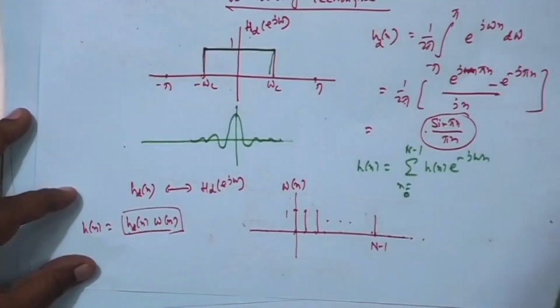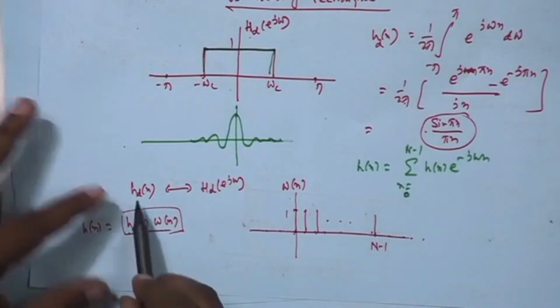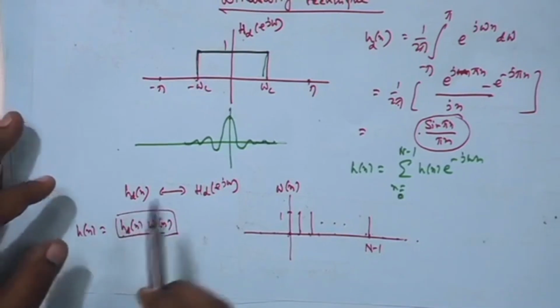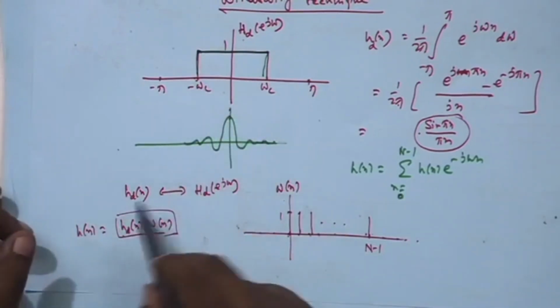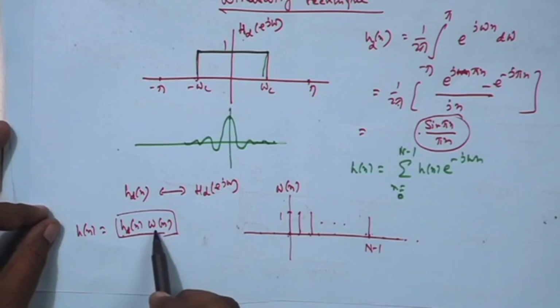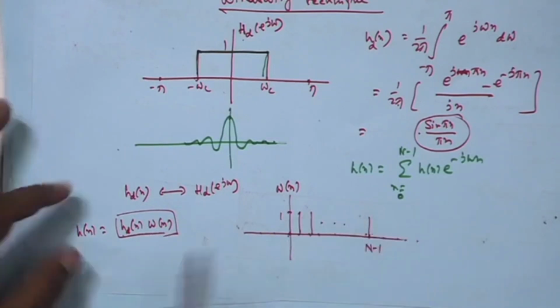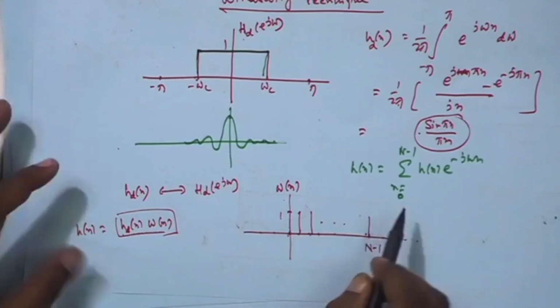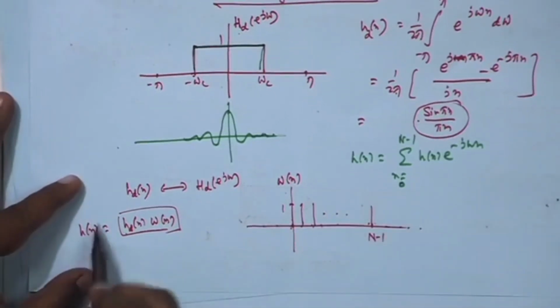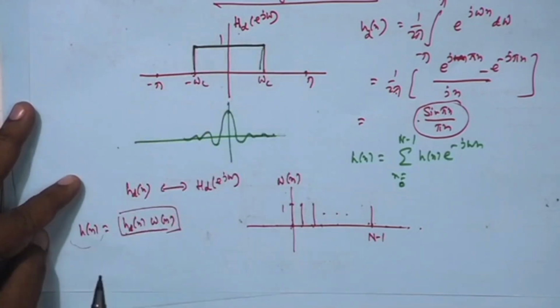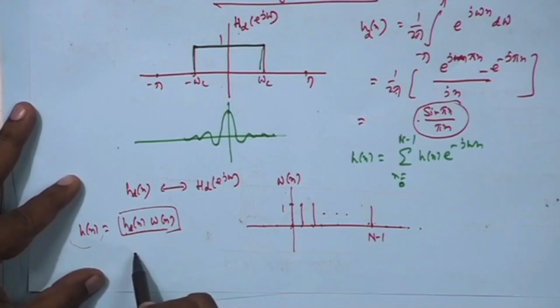All right. Now, I am multiplying this h_d[n], the original in general IIR sequence, which is the inverse transform of any given response H_d, by the rectangular window, of length N. So, only these samples of h_d[n] are retained, others are 0. So, what will be the DTFT of this product? It will of course not match the ideal, desired one, but what will it be?